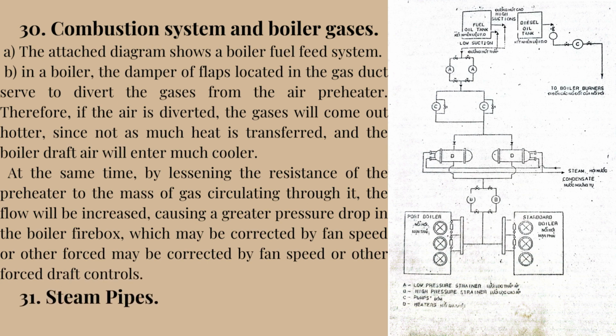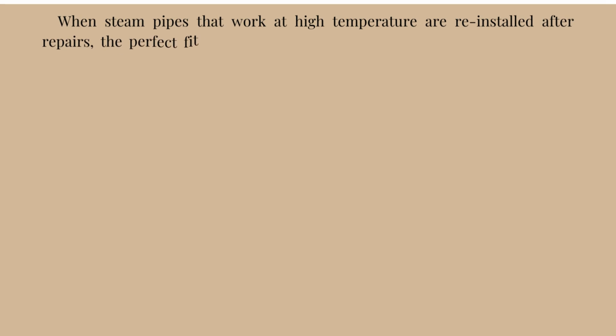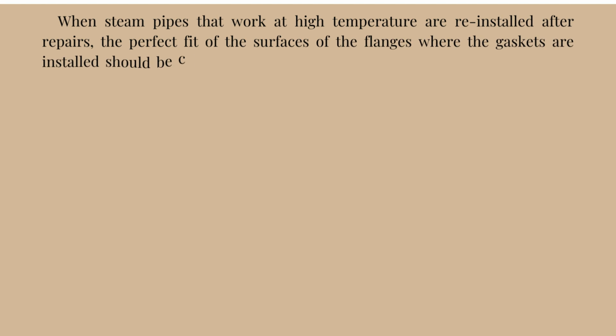draft controls. 31. Steam pipes. When steam pipes that work at high temperature are reinstalled after repairs, the perfect fit of the surfaces of the flanges where the gaskets are installed should be checked. Otherwise there will be leaks through these gaskets.